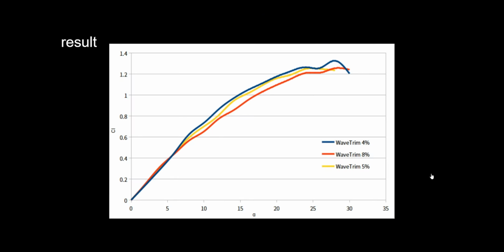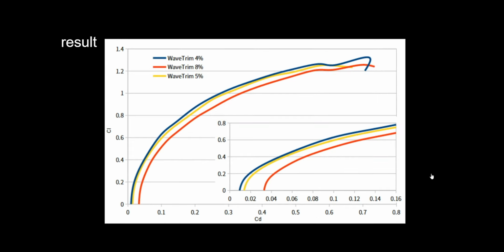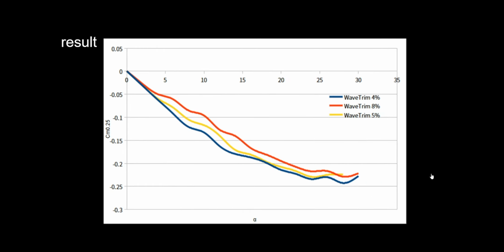Clearly you can find that thickness is the most important factor of supersonic drag, because thickness directly impacts wave drag. In the CD-CL graph, the drag at zero angle of attack is kind of like an offset of the curve, and it also heavily affects the maximum lift to drag ratio. So in supersonic you should always try to make your airfoil as thin as possible.